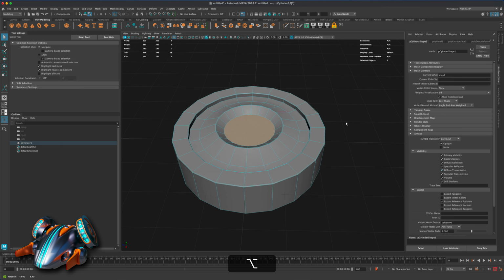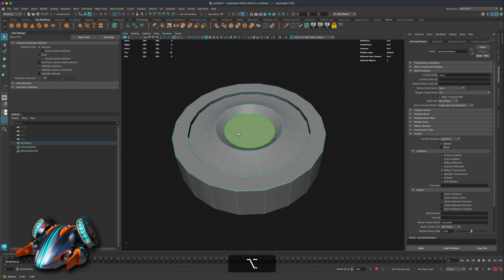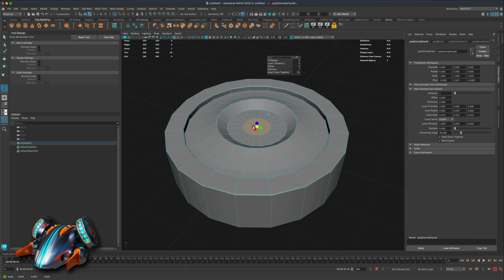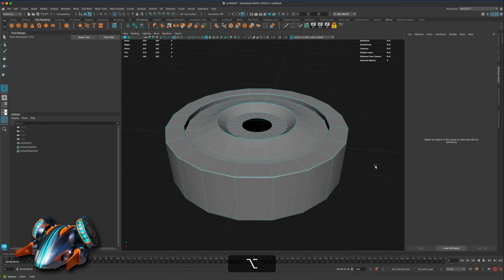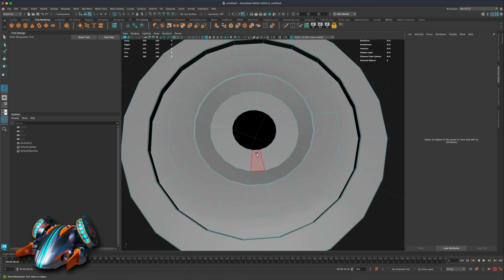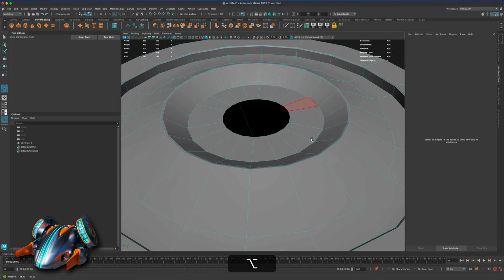So right now, he is one ginormous face, right, with all these different edges. So what I could do is I can do Ctrl E, I can pull him in, something like that, and then I can press delete. Now, the reason I deleted it is because I don't want that face with all those edges looking the way it did, right?